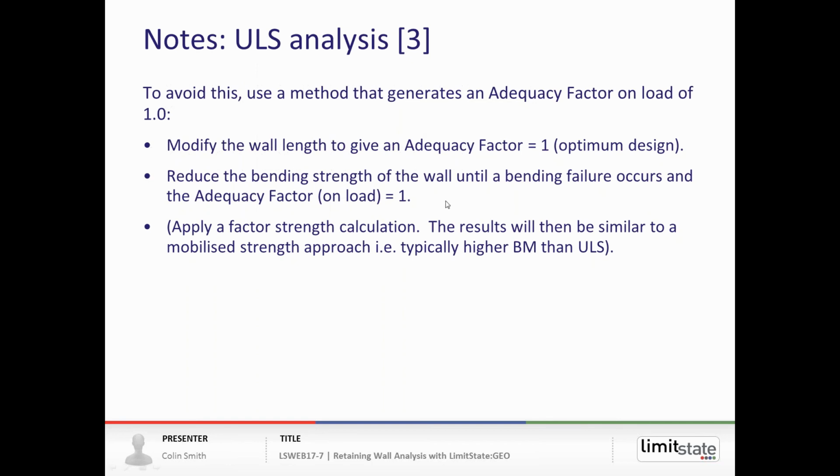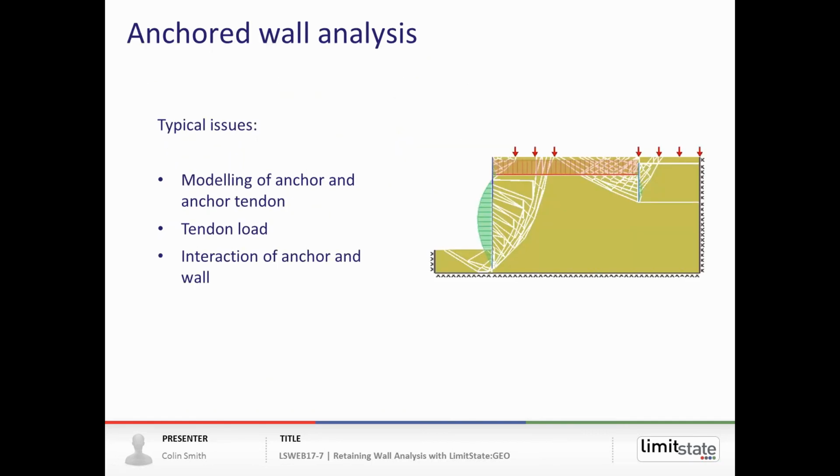Or finally, we could actually do a factor strength calculation. That doesn't change the factor on the loads, but the results we get will be similar to a mobilized strength approach. So typically when you're using mobilized strengths, we're getting more towards a sort of serviceability limit state type analysis, and we're typically going to get higher bending moments. But I think the first two are the better approaches in this case.